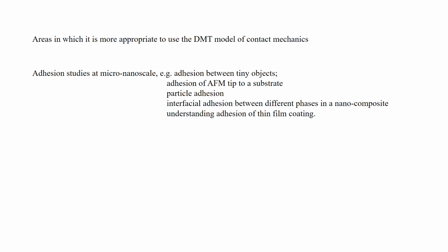As we say, there are several areas in which the DMT model will be useful in contact mechanics or in adhesion. In the case of adhesion, normally we deal with soft materials, so we tend to use JKR. But there are also many applications like AFM adhesion on a substrate, adhesion between two tiny objects, or particle adhesion, for example, where R is very small.